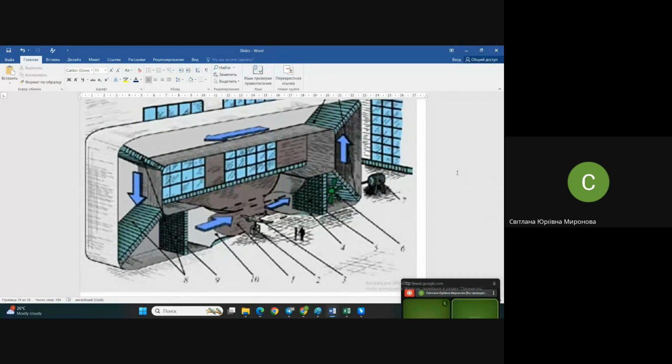They depend only on shape and on position of profile in space, angle of attack. And the whole force, of course, depends on the speed, on velocity of streamline and of air around it, and depends on the type of gas you use due to density of this flow.